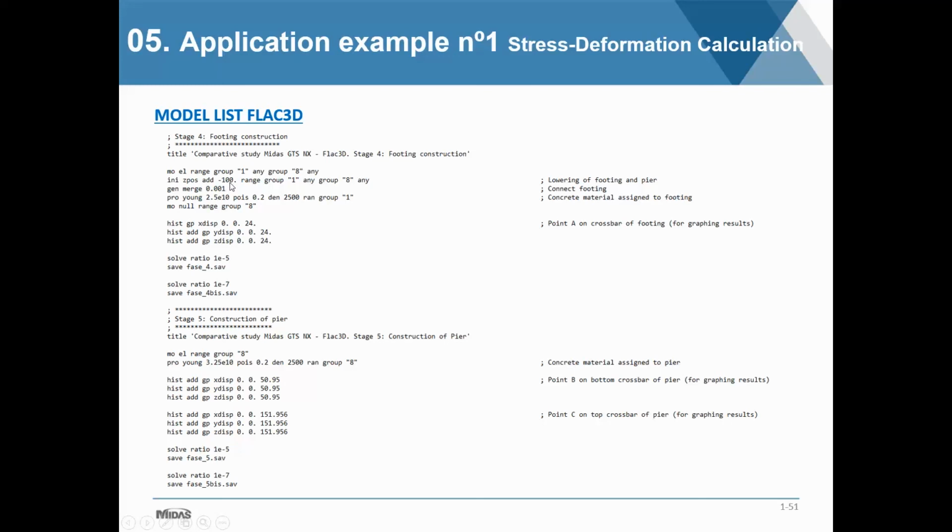So this is where it corrects that the mesh that was imported is in the original location, or in the correct location. So it's bringing it back 100 meters. And then assign the materials, and these are just related to the output. We want graphs to track the displacements in X, Y, Z directions.